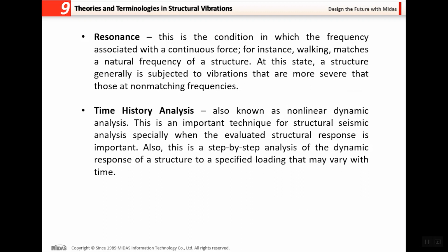So here, resonance. This resonance is actually something most of us don't want to happen in our structure. Resonance is the condition in which the frequency associated with a continuous force, for instance, walking, matches a natural frequency of a structure. At this state, a structure generally is subjected to vibration that is more severe than at non-matching frequencies. So time history analysis.